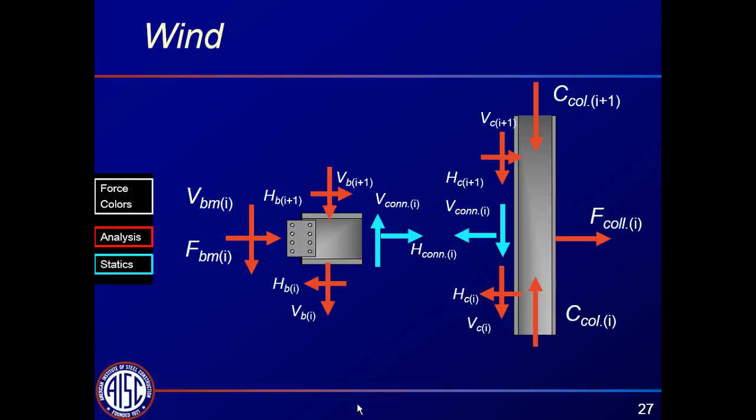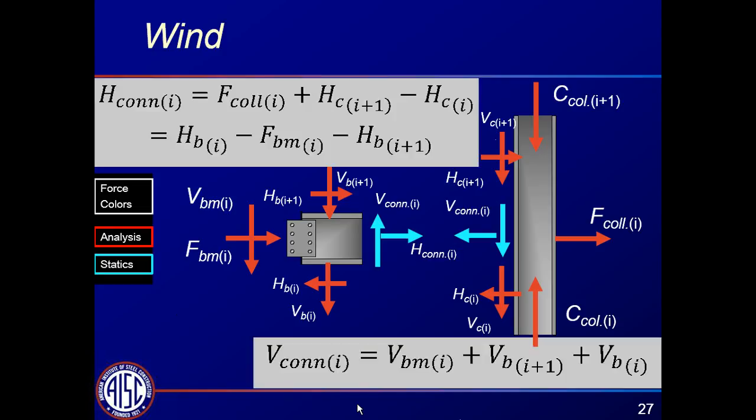So that's the sort of simple analysis that we will do to derive the vertical and horizontal forces. You do that at the left end. We'll be sticking to the left end in this seminar, but of course at the right end, just given the way that we've applied the forces, the gravity force would be additive to the beam shear. So that's all I'm showing in this slide. If you look at it on the compression column, that may be the governing case for the shear and the connection right at the face of the column.